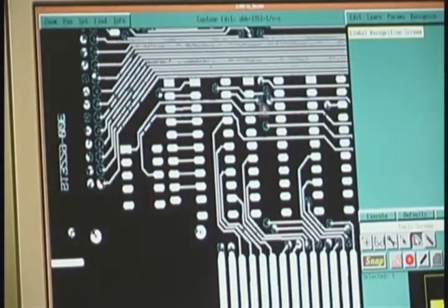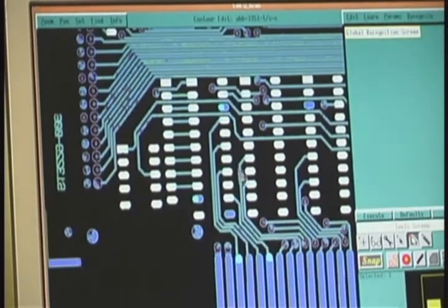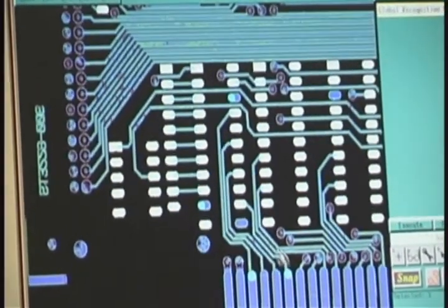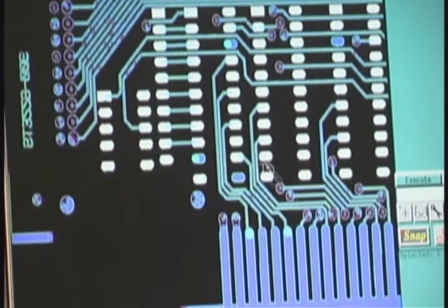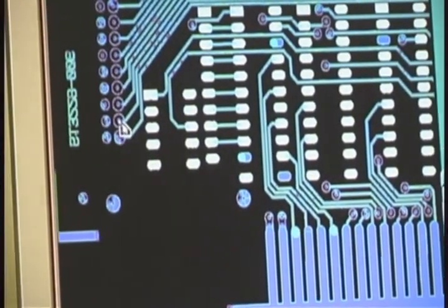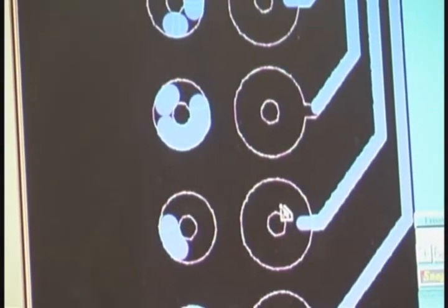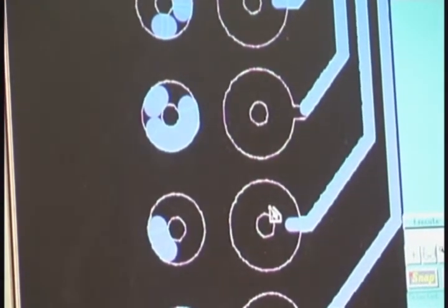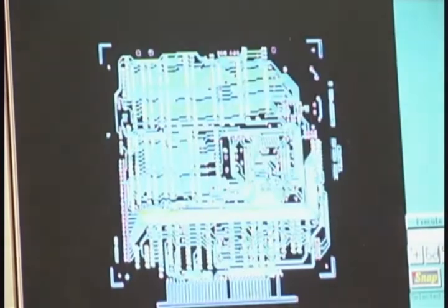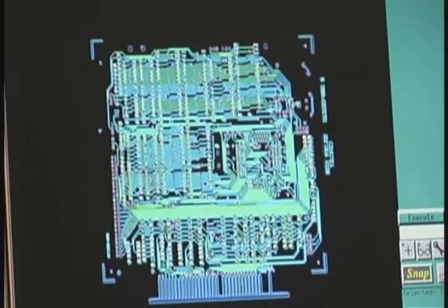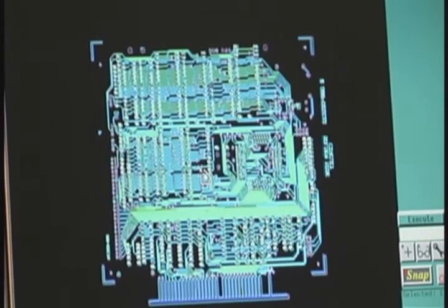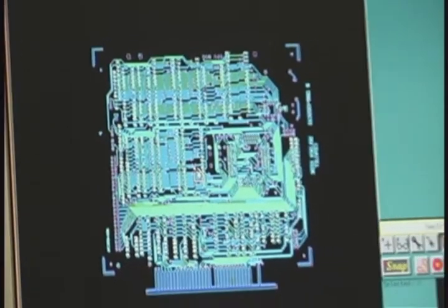After we do that, you can see how you have flashes, you have vectors, and you have areas, what we call areas. As you can see here, because I didn't remove the hole center, it didn't recognize the flash that goes there, the pad.